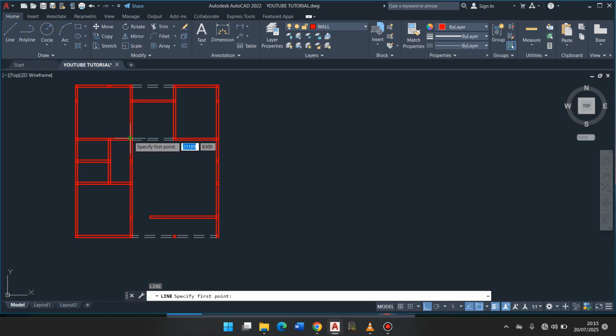Again, we do the same for this part. Click from the beginning of where you want to begin from, preferably from the wall. Yes, so this standard room size is your 900, the width is 150, then you end it, because you can do everything before you decide to trim. The door for the bedroom is normally 800, so the wall width is 150. The same thing for this part, 800. Enter.